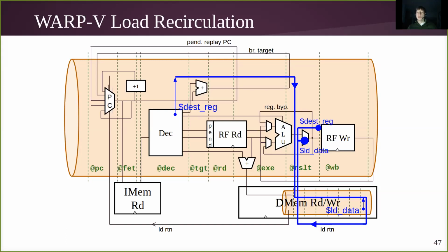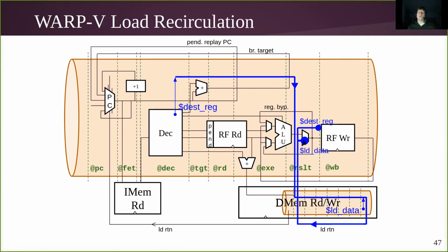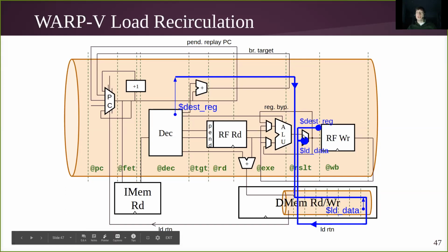The memory is implemented to be in order and fixed pipeline latency, but it's set up to support variable latency out of order. So load instructions travel through the main pipeline and then issue out to the memory pipeline, and sometime later come back into the main pipeline in order to write their result back into the register file. And there's some complexity in the CPU pipeline to reserve a slot for this write back. But as far as the verification is concerned, what's relevant is that we have this path through memory that needs to come back to write the register result.